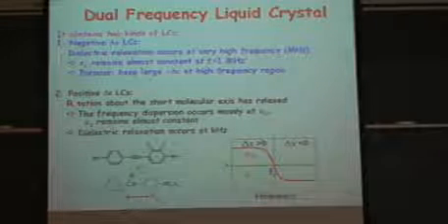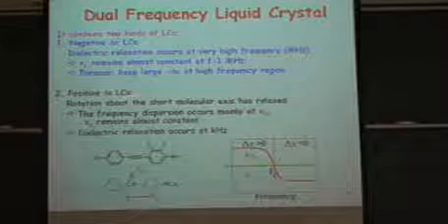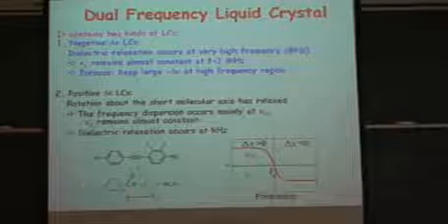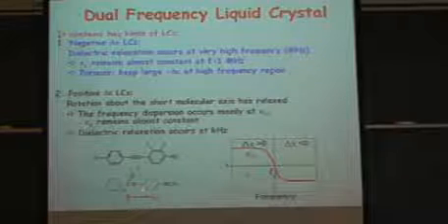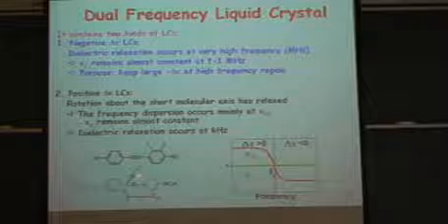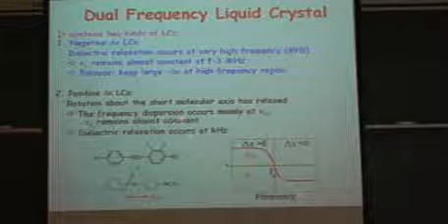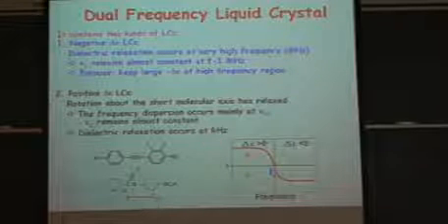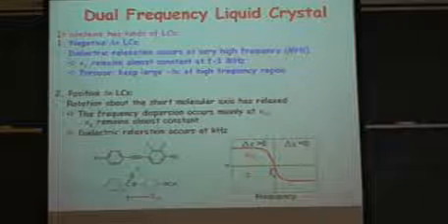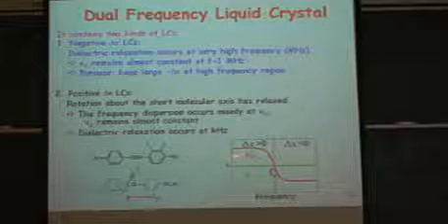And for positive delta epsilon LC, we usually use this structure with the ester group for dual frequency. It has dielectric relaxation at kilohertz. So that's usable for our application.